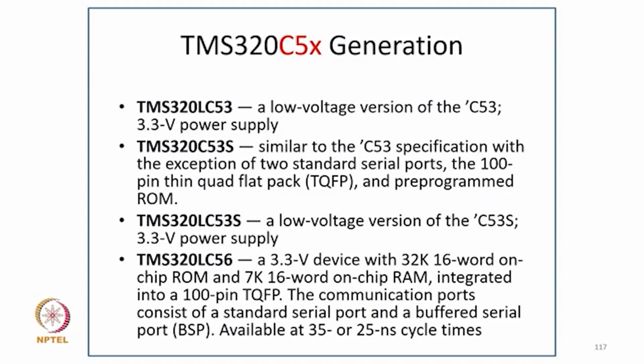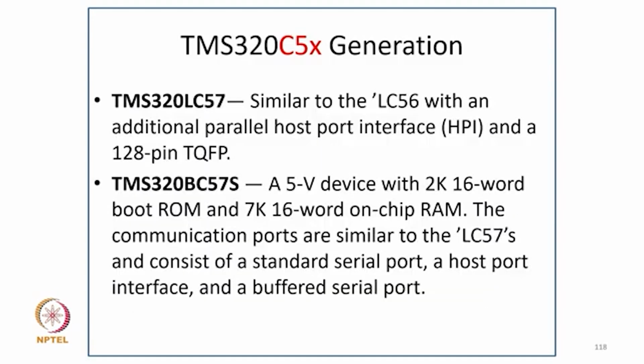volt supply, and TMS320C56, a 3.3 volt device with 32K 16-bit on-chip ROM and 7K 16-bit on-chip RAM integrated in a 100-pin TQFP. The communication ports consist of a standard serial port and a buffered serial port, DSP available at 35 or 25 nanosecond cycle time. So TMS320LC57, similar to the LC56 with the additional peripheral host port interface (HPI)